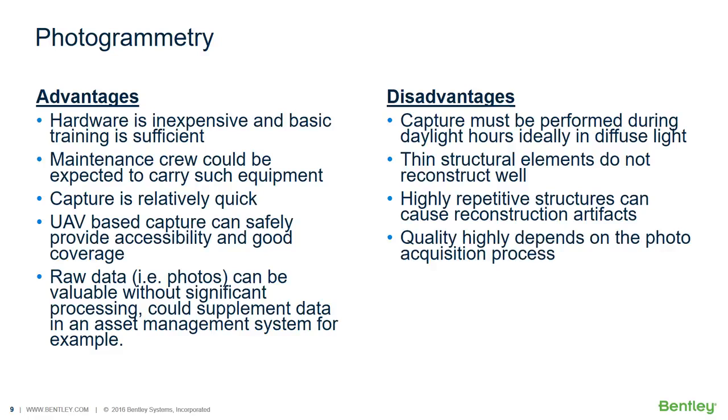Quality highly depends on the photo acquisition process. So although I say it is very easy to acquire your photos, you do need enough overlap. You need to make sure you cover enough area, and basically every part of the scene that you want to model, you need to have several photos of that cover that area. We do have an acquisition guide which easily helps you through that.